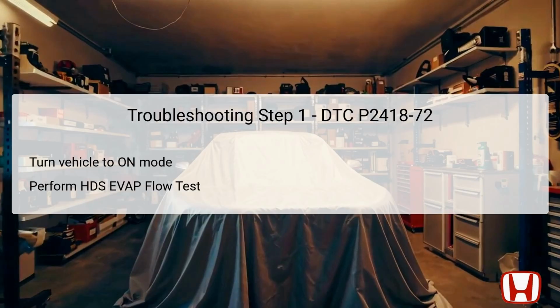The first step in troubleshooting DTC P2418-72 involves turning the vehicle to the on mode. This action activates the electrical systems without starting the engine, allowing diagnostic tools to connect and gather necessary data. Next, the HDS, or Honda Diagnostics System, performs the EVAP purge flow check test.